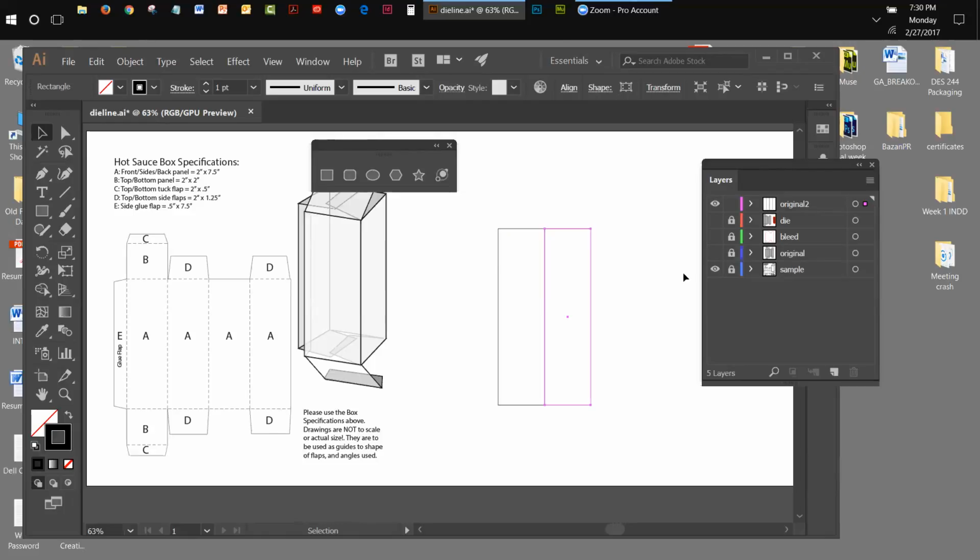No. Okay. Now what I'm going to do is the same thing. I'm going to select both of these guys by marquee. You know what a marquee is, right? Where you drag through both of the items to select it. Yep. All right. I'm going to come back over here, hold the Alt key down again, hold the Shift key again, and drag these up. I didn't get it right. Hold on. Let me hold down the Shift key and the Alt key, and now let me drag these 2 guys. Oh, geez. Now it's not going to let me do it. Let me select it, click the Alt key and start dragging it. Hold the Shift key down. There we go. And now I'm going to drag it over here until I get the intersect again.